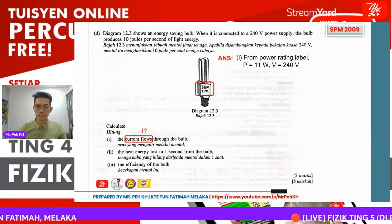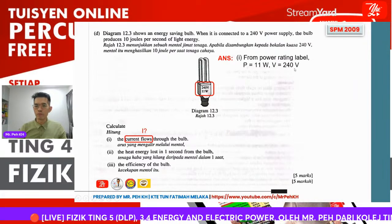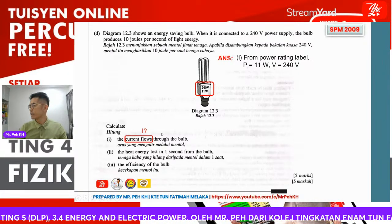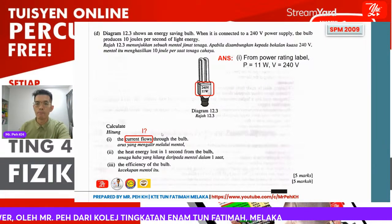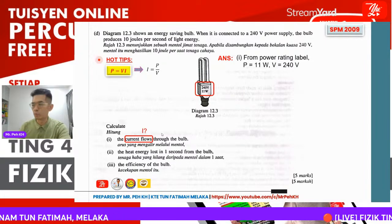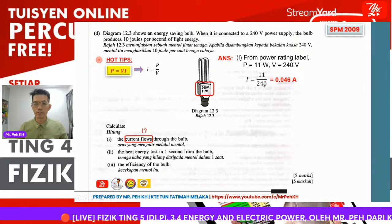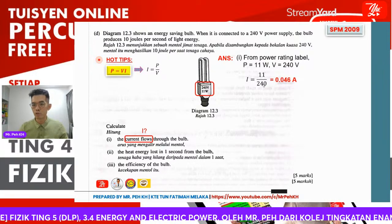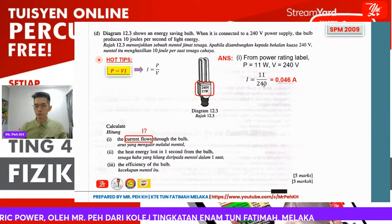Then the question gives us the power rating, which is labeled with P equal to 11 watt, and V equal to 240 volt. So P, V and I, what's the formula we should choose? Just as we learned already, we should choose P equal to VI. Then we rearrange to become I equal to P over V. You just substitute the values, 11 over 240, so you get 0.046 ampere. Make sure you give minimum 2 decimal places with the correct unit for your final answer.